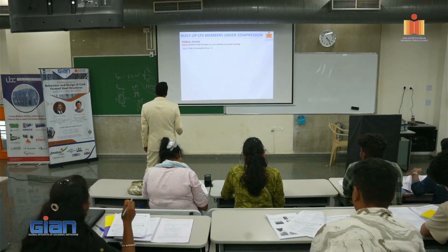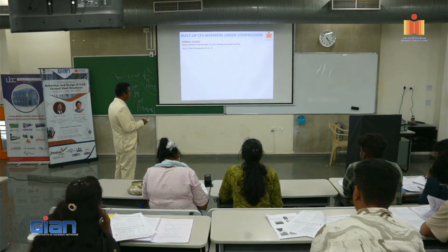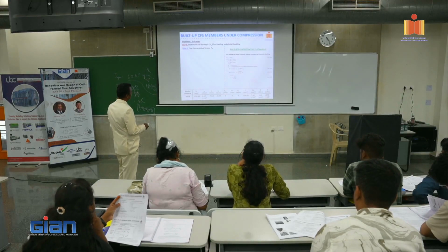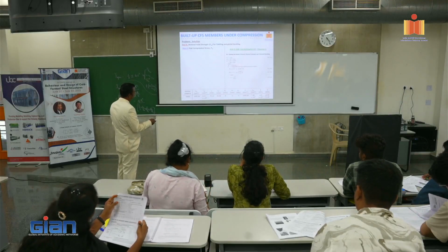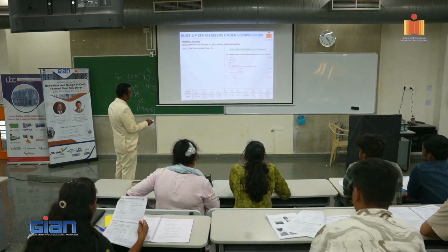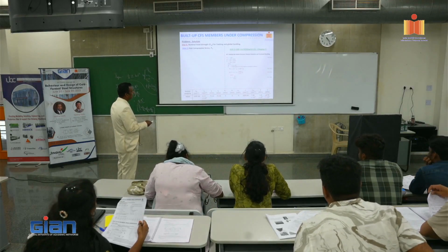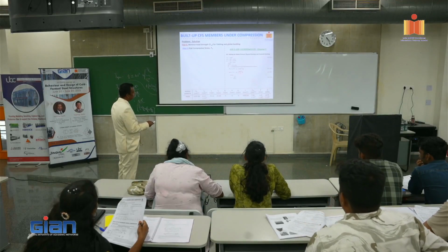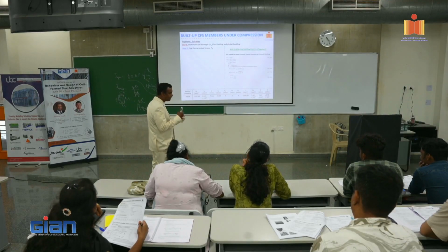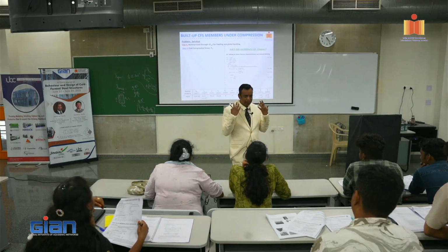So for the nominal axial strength, PNE, for yielding and global buckling, we have to calculate Fn. Right? Which is the nominal compressive stress. The nominal compressive stress, right, is given by this equation. This equation in chapter E says that if lambda sub c is less than or equal to 1.5, you use the topmost equation, 0.658 to the power lambda c square into Fy. If lambda sub c is greater than 1.5, Fn equal to 0.877 divided by lambda sub c square, times Fy. So what is it? 1 by lambda sub c square. Does it ring a bell? When something slenderness square is in the denominator, does it ring a bell? What does the curve look like?